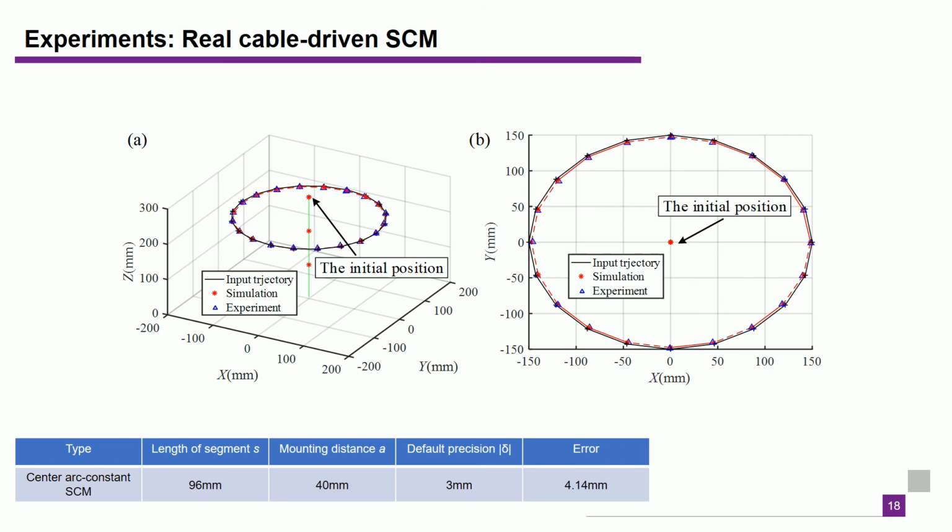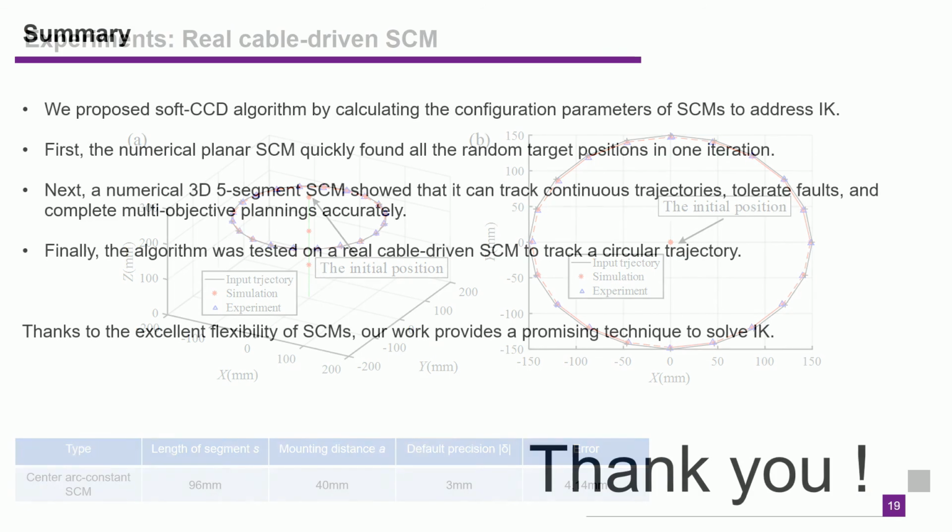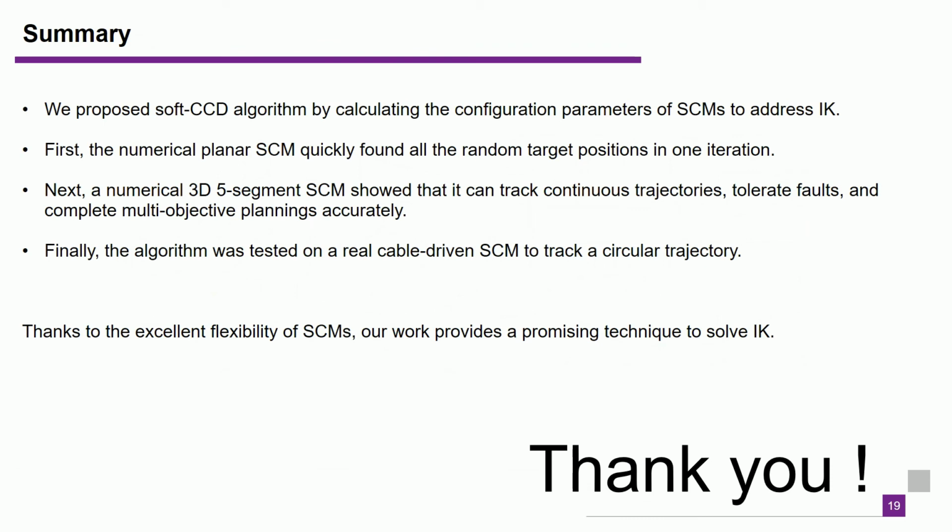The tracking result is shown, and the maximum error is 4.14 mm, which is mainly caused by the assembly error and driving accuracy. To sum up, we proposed the Soft-CCD algorithm by calculating the configuration parameters of SCMs to address the inverse kinematic problems. Based on Soft-CCD algorithm, the numerical planar SCM quickly found all the random target positions in